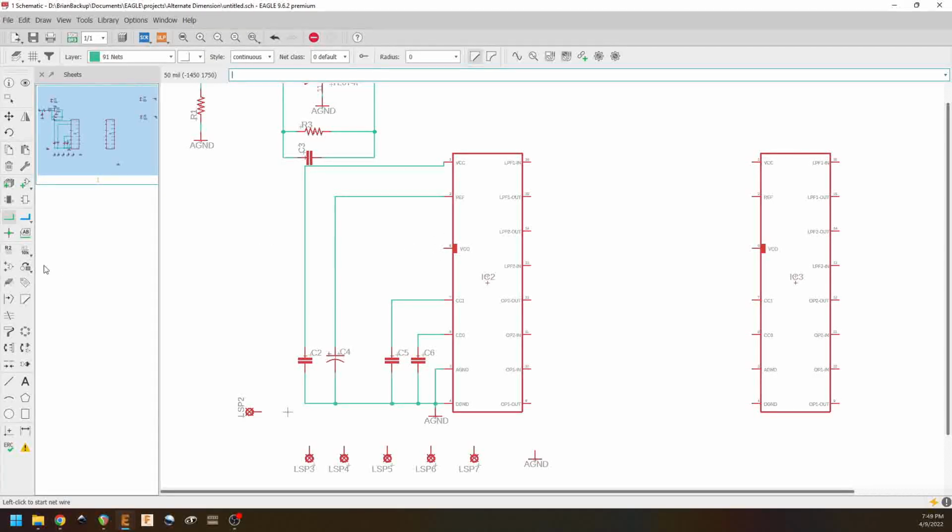We're going to put in a resistor here. This resistor is going to make it so that there is a minimum amount of resistance on our time control pin, because with a PT2399, if you don't have a minimum amount of resistance, the chip can actually lock up and it's not going to work well for you.